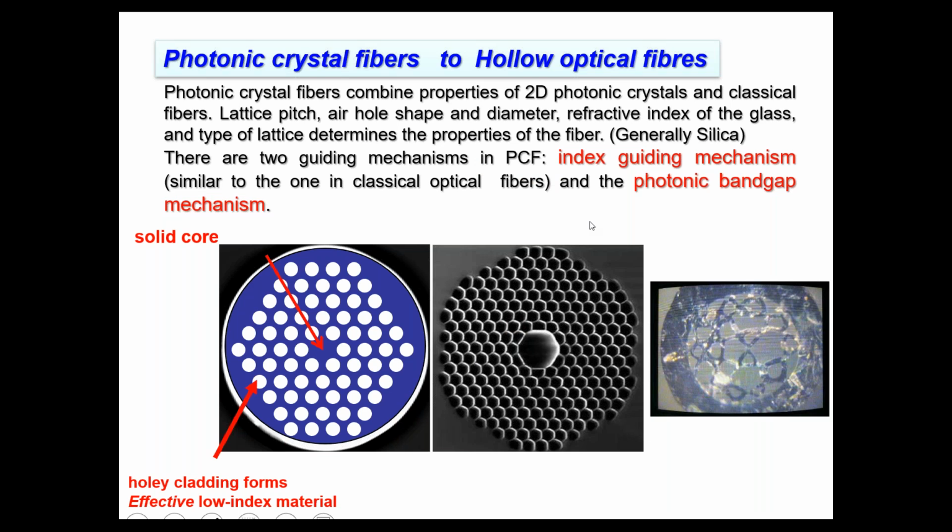But here you can have a variable value of the core and cladding refractive index. The core refractive index remains the same, while the cladding refractive index can be continuously varied in accordance with the change in lambda, so that it will accommodate the changes in the V parameter, so that the light will continue to be in the single mode, or the operation will continue to be in the single mode regime.